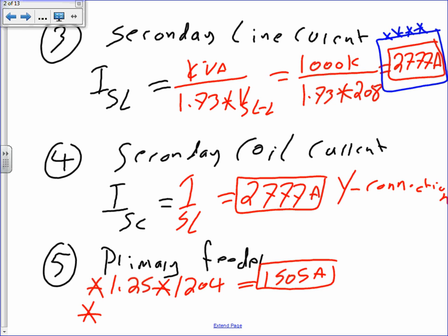So 3, 4. I use 4. You can use 3. 3, I think, would probably give you 600 amps, 600 kcmil. But I decided, now on the test, if you did 3, would it be wrong? No. Okay, so divided by 4. When we did that one, it gave me a value of 376 amps.